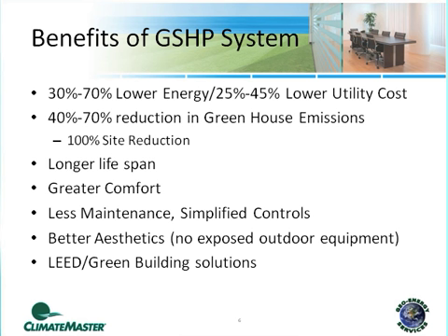We also have longer lifespans. There have been some studies done over the years that have proven that ground source heat pump systems have a longer lifespan on the equipment. The vertical borehole ground heat exchanger actually has a long life based on the plastic pipe that's out there, and if the engineers designed it correctly, it will last indefinitely, or at least as long as the building will last.